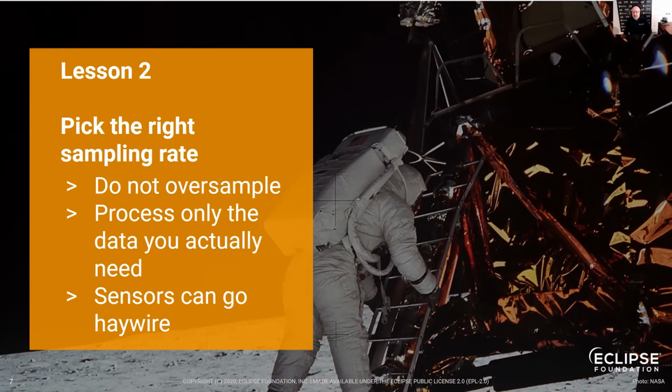The recent problems with the Boeing 737 are a good example of that. I mean, it's an incredibly sophisticated plane, but it had only a single sensor to measure the angle of attack. Okay, and that led to the two catastrophes that happened with two of those planes. Since the sensor was defective, it was returning erroneous data to the computer, and the computer was running software that wasn't appropriate for the current situation of the plane.